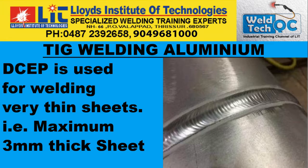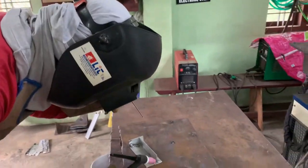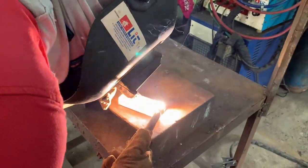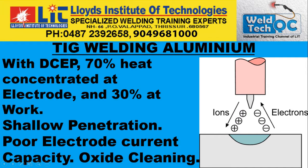DCEP is generally used for welding very thin sheets, and can weld a maximum of 3 mm thick sheets. With DCEP, let us see what happens. With DCEP, 70% of the heat is concentrated at the electrode and 30% at the work. The penetration is shallow, and the current carrying capacity of the electrode is very poor. So you will have to use a larger electrode if you are using DCEP, and the oxide layer cleaning is available with DCEP.